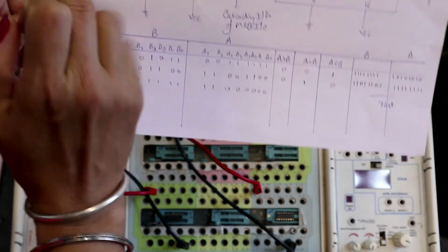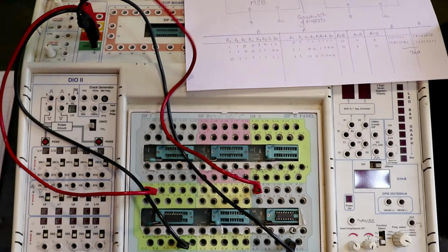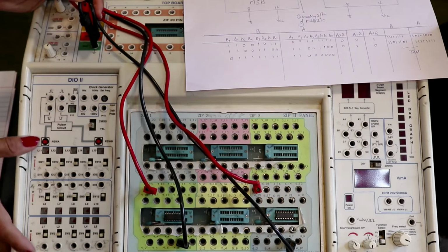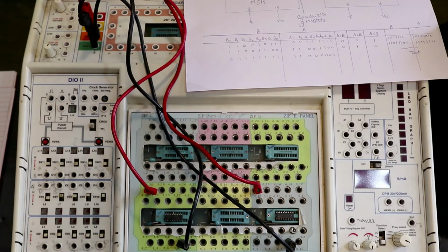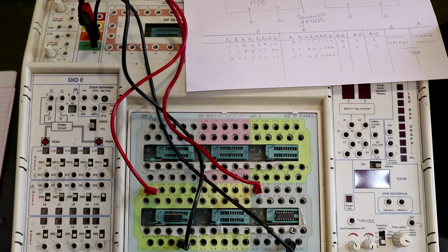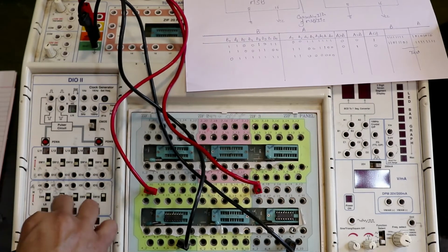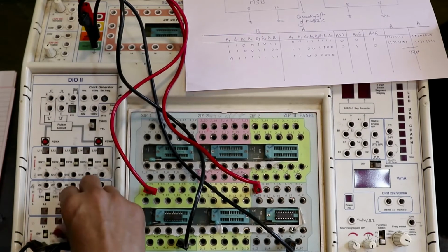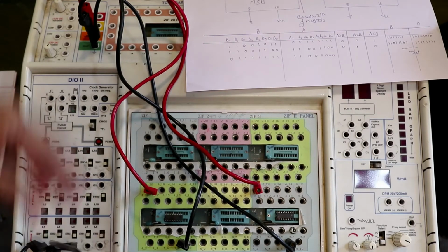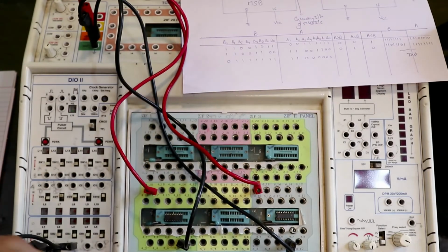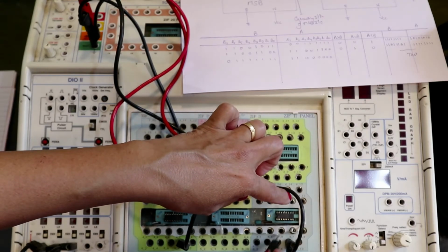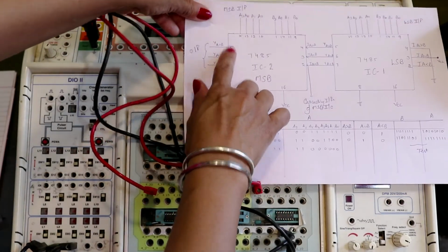Next, for the second IC, we make the connections for the outputs. On this board we know this is the input and output section, so we can treat any row for input and any row for output. Suppose here I use the last row for output. I make the connection here, here, and on this notch. Yes, perfect. The first connection is on the 5th pin of the second IC. Where is the 5th pin of the second IC? 1, 2, 3, 4, 5. So I have finished this connection.